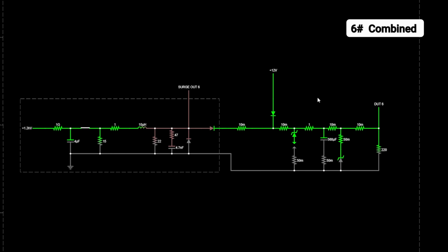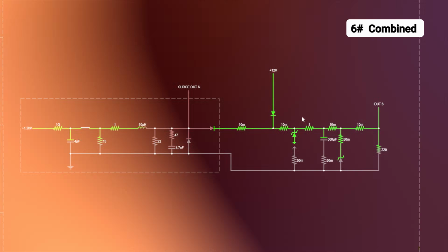There are also ways, and this will probably be another video I'll do, of having an E-fuse or a back-to-back MOSFET array in conjunction with this circuit to help disconnect the rest of your circuit in the event that there is a surge too great or too powerful for this main 3-layer approach to be able to protect against.